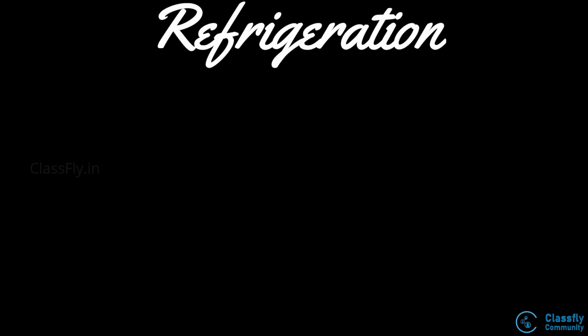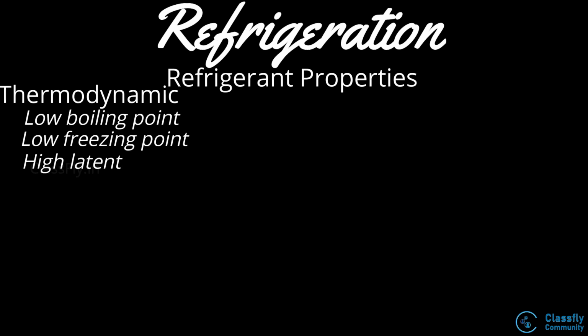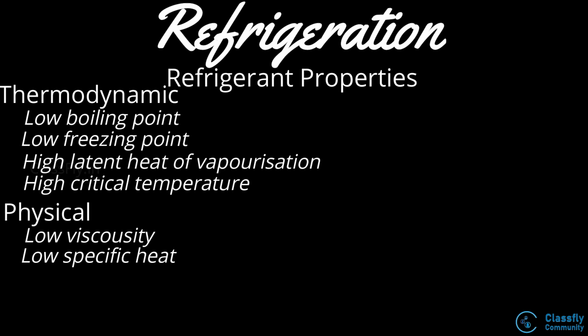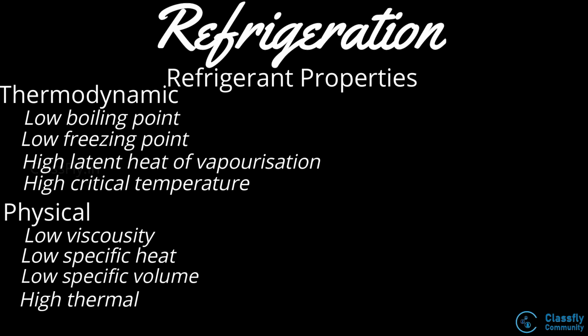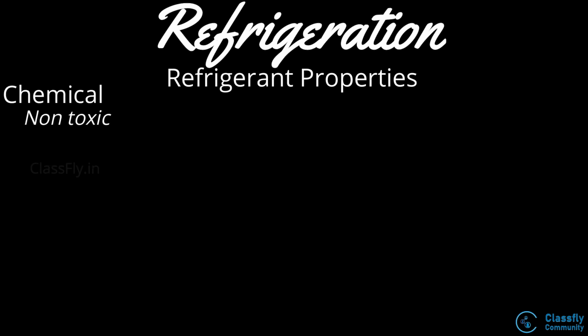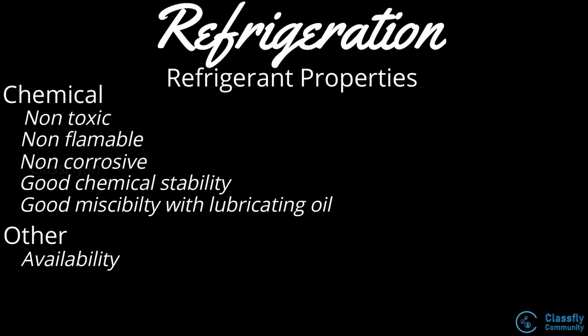Well, we studied several properties of the refrigerant such as the thermodynamic properties, which included low boiling and low freezing point, high latent heat of vaporization and high critical temperature, physical properties such as low viscosity, low liquid specific heat, low specific volume, high thermal conductivity and high electric insulation, chemical properties such as non-toxic, non-flammable, non-corrosive and good chemical stability and miscibility with the lubricating oil, and also other properties such as availability, cost, ease of handling and impact to the environment.